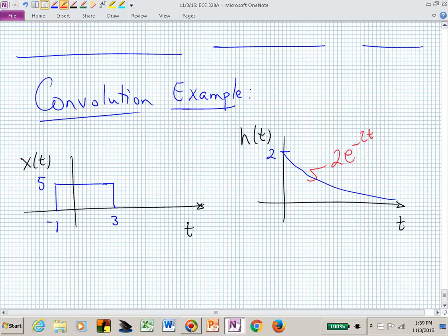What kind of a system is that impulse response associated with? A first order. And you could consider it a low-pass behavior. It's this exponential shape that has actually a pole at s equals minus 2. You know that just by looking at the exponential.